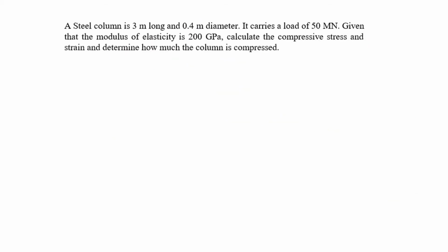Okay, so for this one, we've got a steel column that's 3 meters long and this much in diameter. It carries a load of that. Given that the modulus is here, calculate the stress and the strain and determine how much the column is compressed.